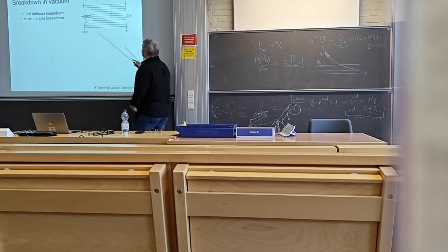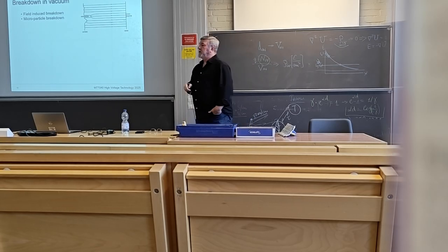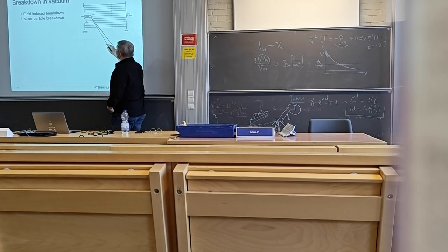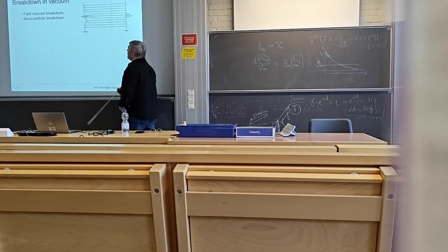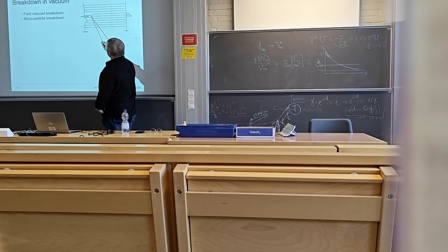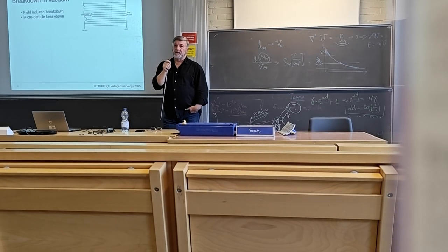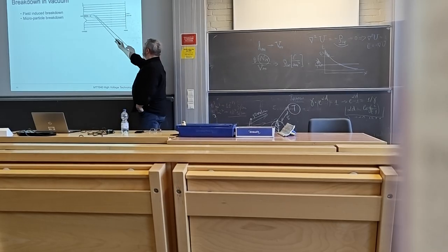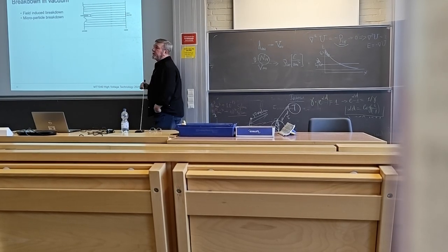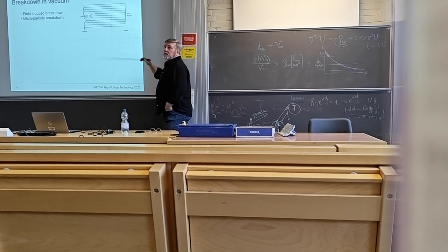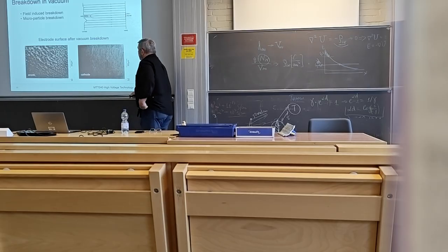So also when the current is concentrated on the tips of the protrusions, the current density is extremely high here. And what happens is it just starts melting because it's overheating, and then produces small pieces of metallic drops, which also, coming to the anode side, create local overheating in the contact area. So what happened then, you may see here,